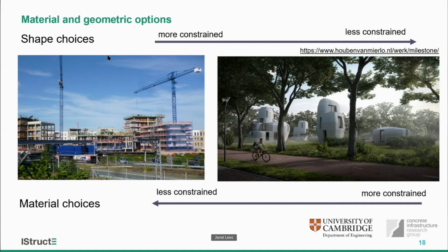It's very complicated rheology, in that the material needs to be fluid enough to come out of the nozzle, but then it needs to gain enough strength quickly to support the next layer of concrete that is deposited on top of it. So the rheology and understanding of concrete is very important in that concept. If we look back at less constrained, to some extent, if we have shuttering, it forgives a great many ills, in that we can make the shapes we wish, and within that we have a wide range of fluidities and rheologies that can be accommodated.